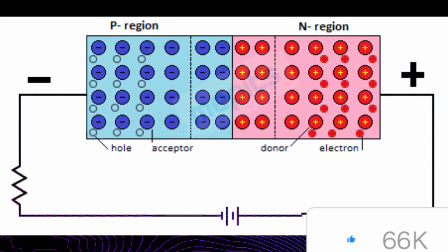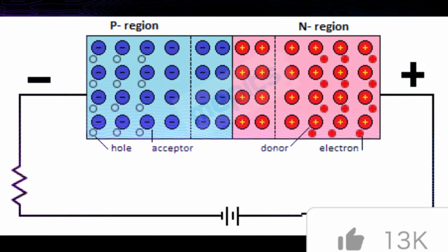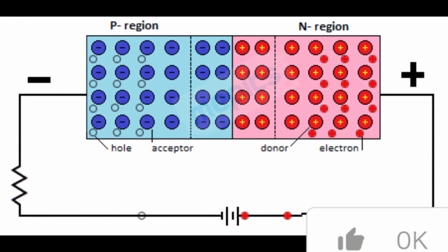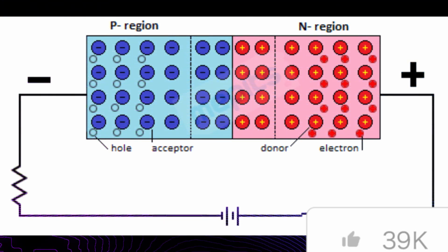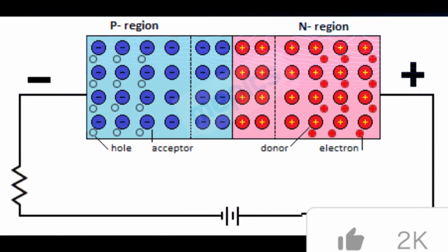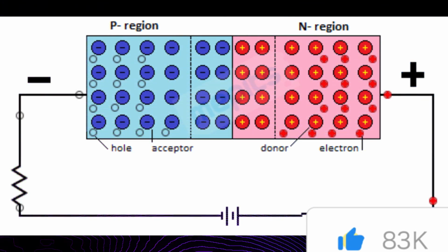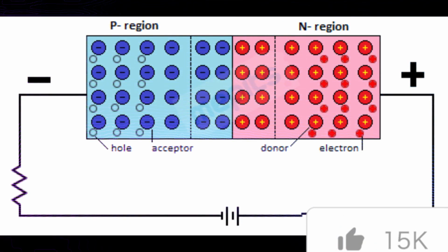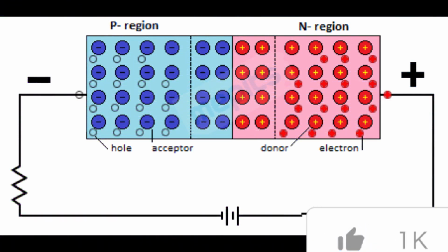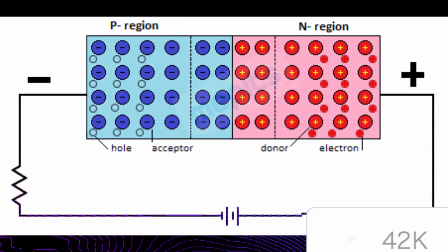A common example of this use of conventional current flow theory is the electrical system of an automobile. Most automobiles today use a negative ground system, which means that the negative terminal of the battery is grounded. The positive terminal of the battery is considered to be the hot terminal, and it is generally assumed that current flows from the hot terminal to ground.